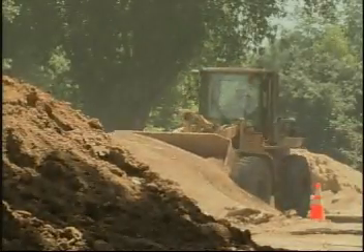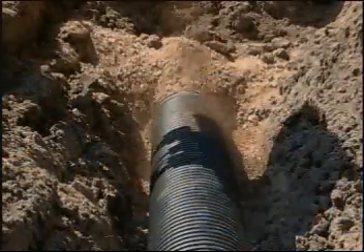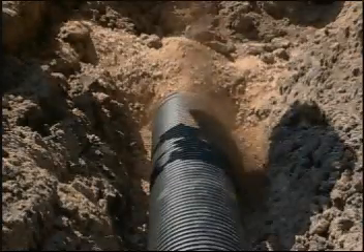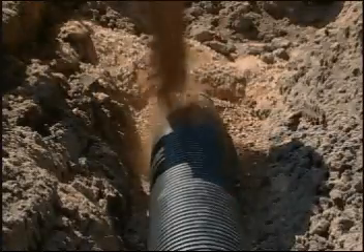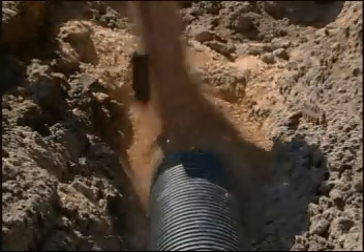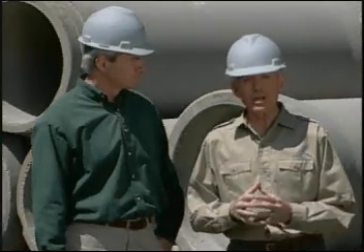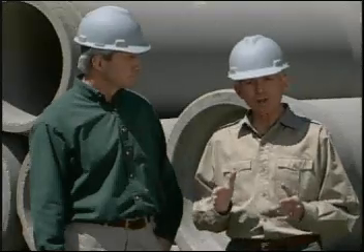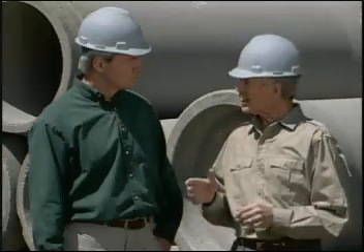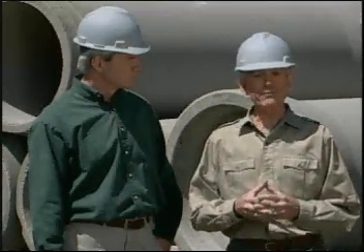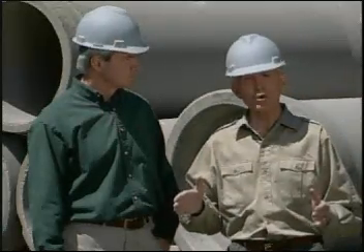The pipe system structure, which is provided by a combination of the pipe and the supporting soils around the pipe, must maintain sufficient long-term strength to protect the viability and dependability of the conduit. Rigid pipe, like concrete pipe, is designed and manufactured so that the pipe will provide most of the required structural strength in the pipe soil system. Frequently, RCP will provide 85 to 95% of the required structural strength in that pipe soil system.